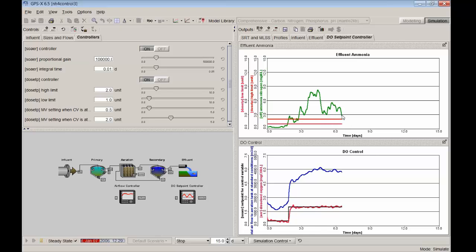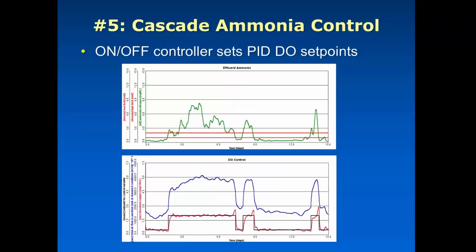And then when we get to a point when this ammonia is going to come back down, it's going to drop that down again. And just to speed things up a little bit here, I'll take a screenshot of what I had all the way through. So as the system responds back and forth, you can see that it takes the opportunity to not only turn down the airflow in the sense that it responds to a change in the load, but it also looks at a change in the effluent. So it even says that when there's nothing coming out in the effluent, or it's doing its job, there's an opportunity to even back off the airflow a little bit more.